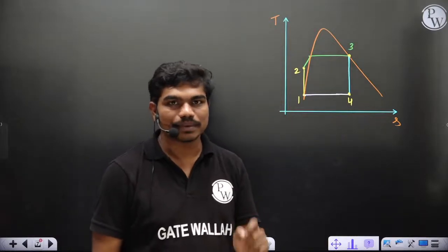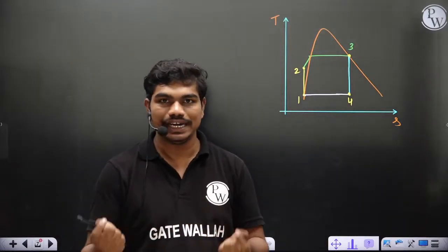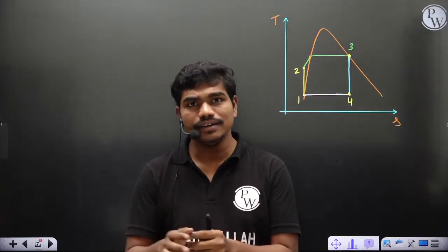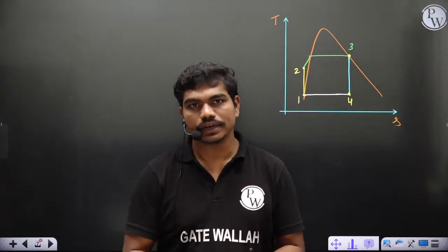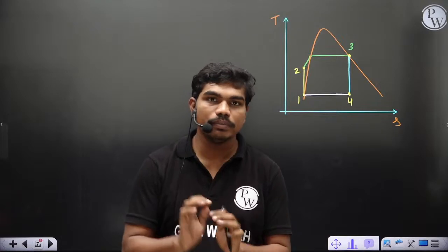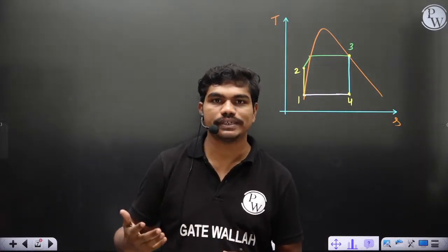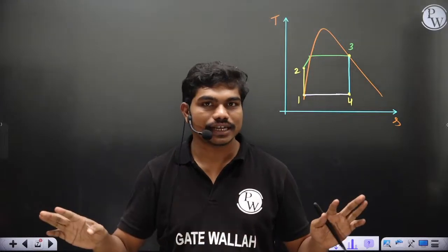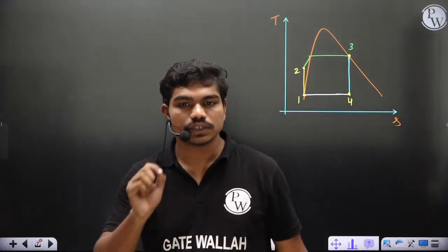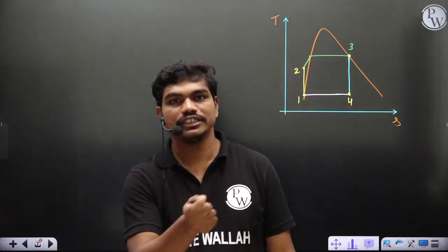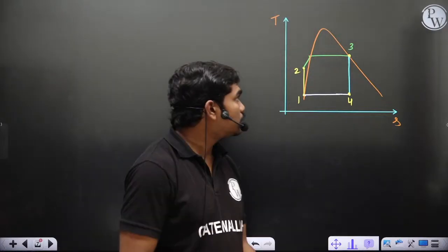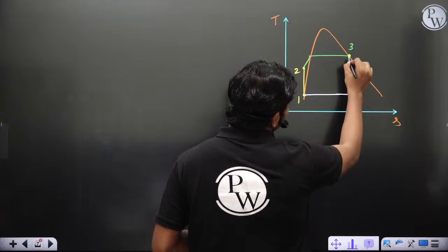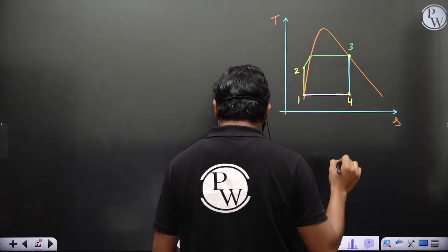But practically sometimes what happens in case of devices, because of heat loss, even if you take any turbine, practically there will be certain heat loss from the turbine. So it's not purely adiabatic, and also because of very high speed expansions, normally turbines operate at 80,000 to 90,000 rpm. At that high speed, nothing is going to happen quasi-statically, so everything is irreversible. That's why we define something called isentropic efficiency for the devices. Clear? So in this expansion, if something is irreversible, entropy definitely increases.